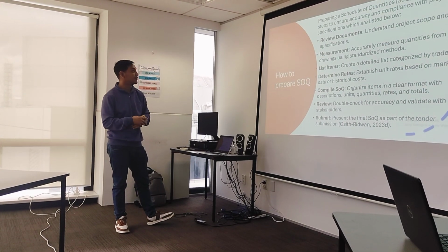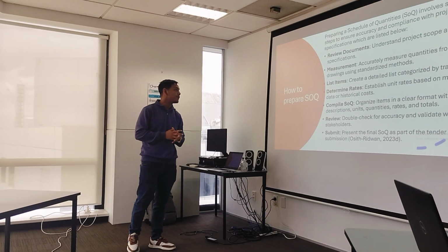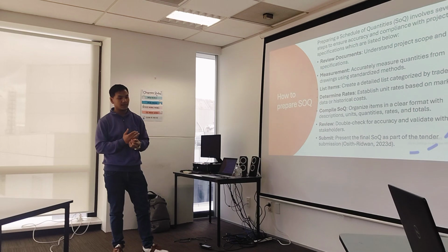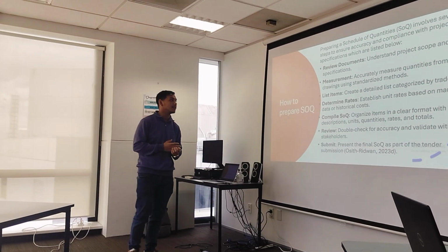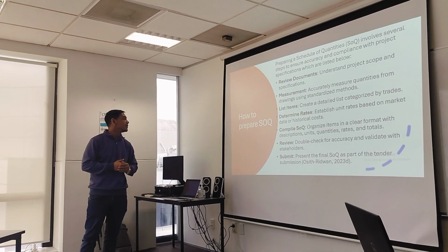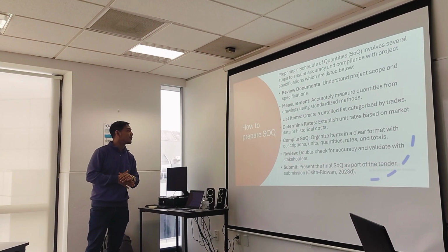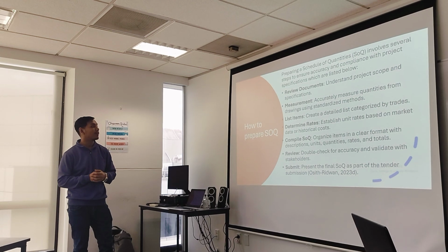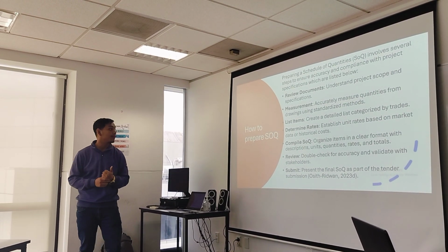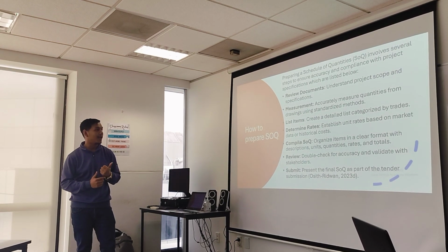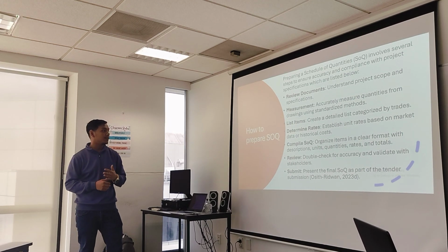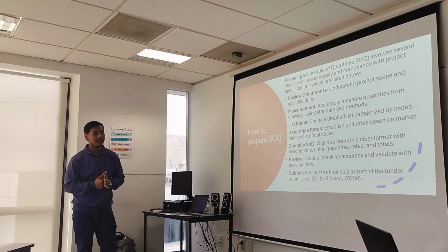How to prepare an SOQ? Before preparing an SOQ, we need to focus on measurement and quantification, abstract quantities and others as per the requirement. We need to review the documents, understand the project scope and specification, and take accurate measurements from the drawing as per the requirement of the standard method.